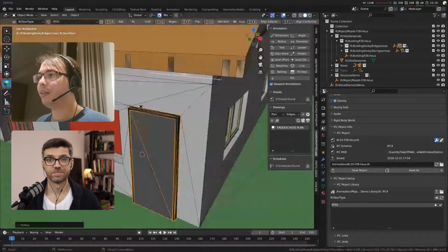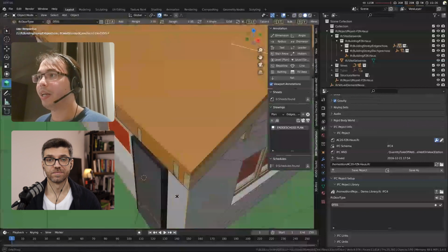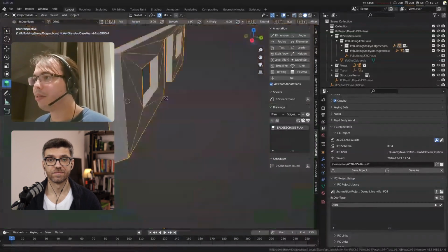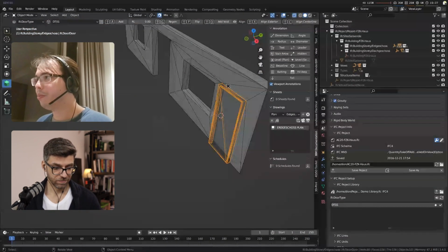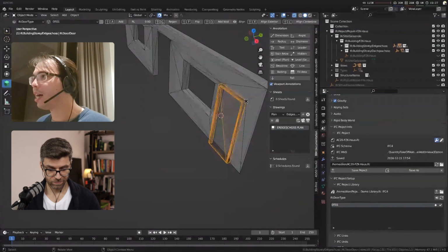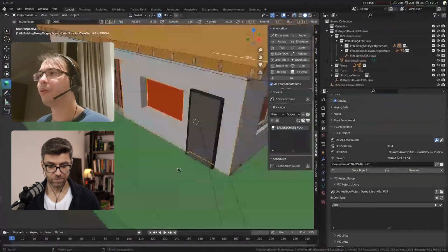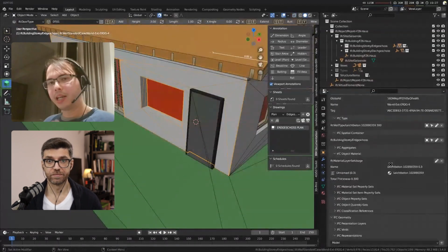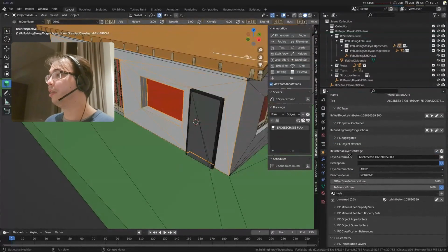Now you can see that the door has actually cut an opening in that wall. So let me just isolate this. You can see that the door has made a cutting, but that cutting hasn't quite gone through the whole wall. So the question is, why? Is that a problem with how ArchiCAD is defining their wall? For example, and this one I know the answer, it is.